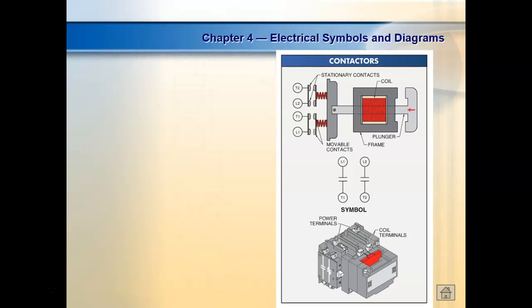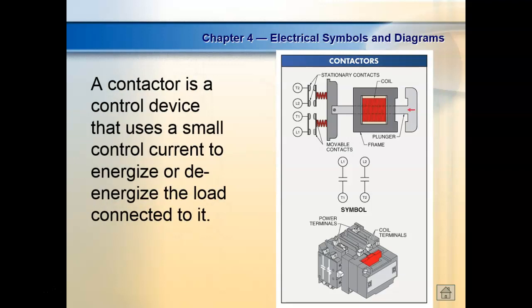So when you buy coils, you have to buy either AC coils or DC coils, and they're rated at the voltage and the frequency that the coils are designed to run at. So if you look at this coil right here, it says it's 120 volts, 60 hertz. If you put it on 240, what would happen? It'd burn up, yeah, because it's going to try to pull 4 times the power, right?